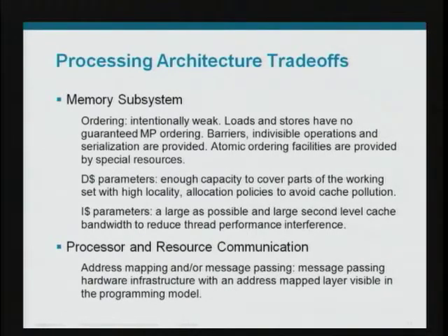Trade-offs in the memory system: ordering is a big deal. You can expend a lot of verification energy, a lot of hardware, a lot of time working on architecture for that. We ultimately decided that for the type of application we're doing, we were not justified in building a strongly ordered system or providing much order in loads and stores. So there is no load and store order guaranteed for multiprocessors. We do provide some barriers and indivisible operations, and some atomic ordering that Will mentioned that goes along with the packet state.